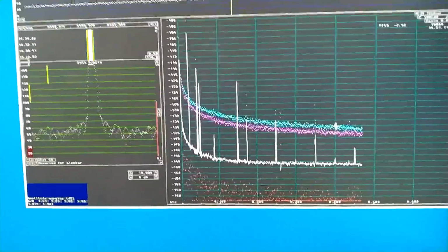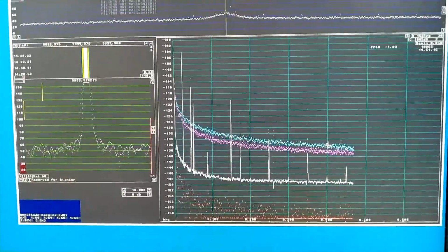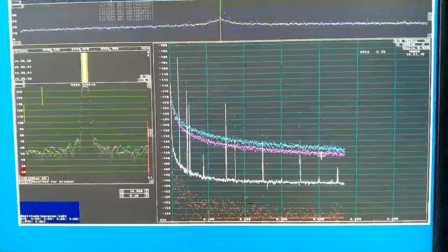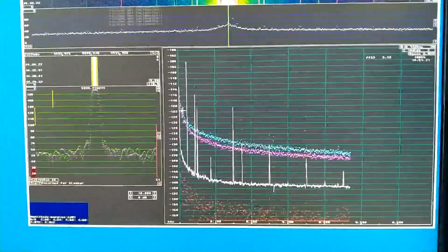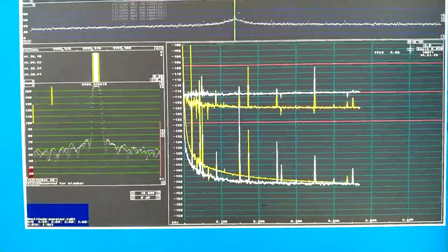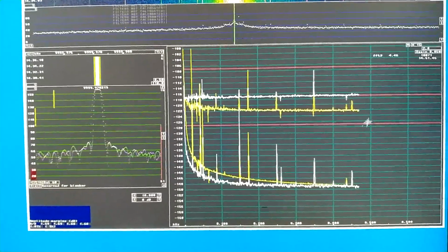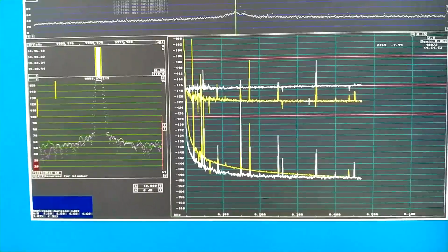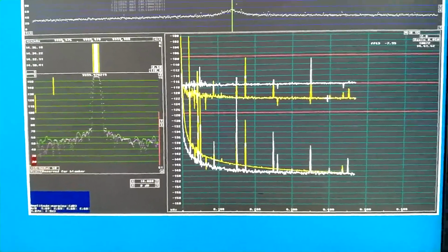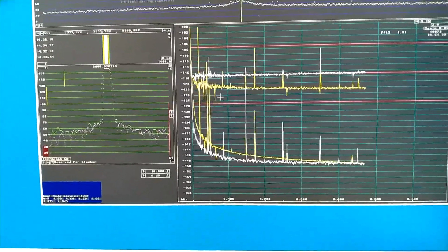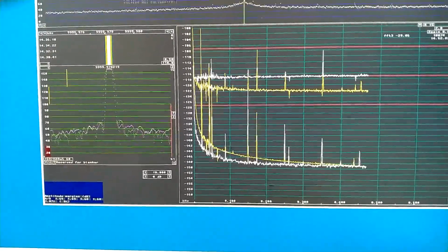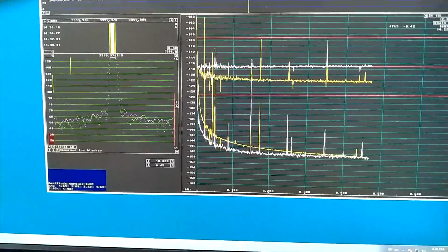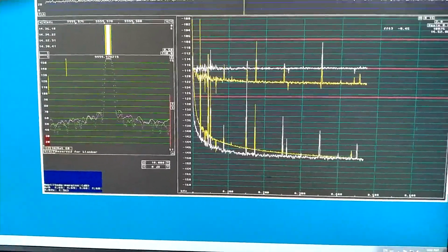The reciprocal mixing noise of the SDR-IP units is not as high at this offset as it is very close to the carrier. And this is intriguing. Even though the amplitude noise is very low, it has a significant correlation with the phase noise already at an offset of 50 Hz. And in here, below 50 Hz, the signal-to-noise ratio is poor. So correlation is noisy.